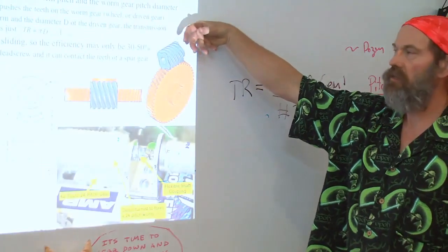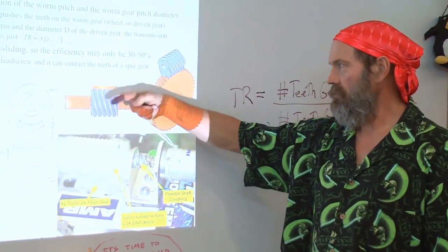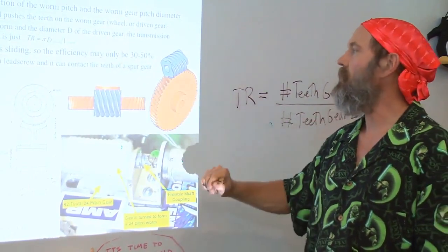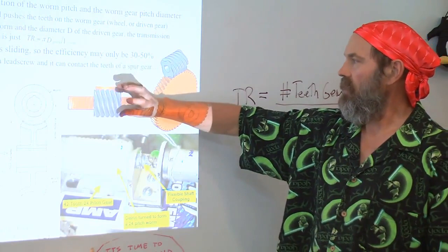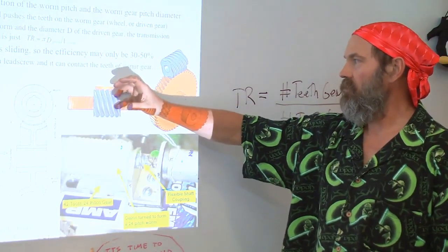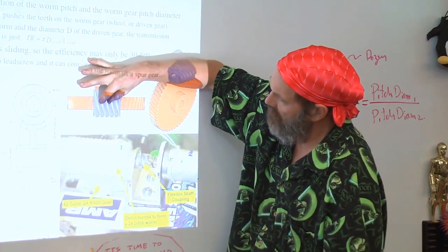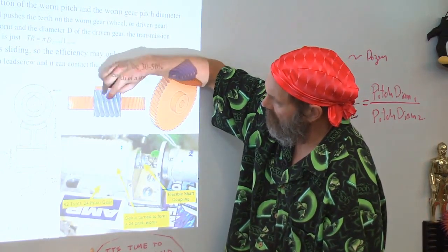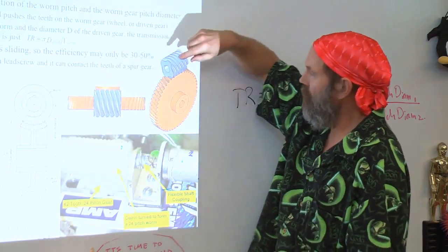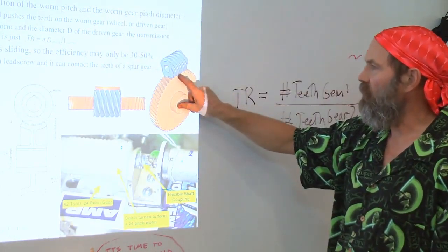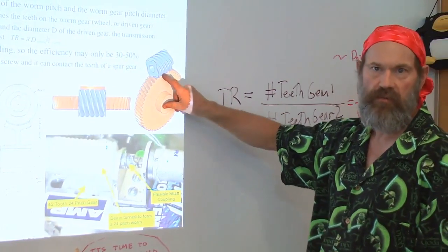It's basically the lead screw principle. And here, the worm, that's the little linear spirally dude, engages the worm wheel such that when I turn the worm one rotation, one pitch, essentially this thread, it looks like it advances to that thread, or on the surface of the worm wheel, it moves forward one pitch of the worm.